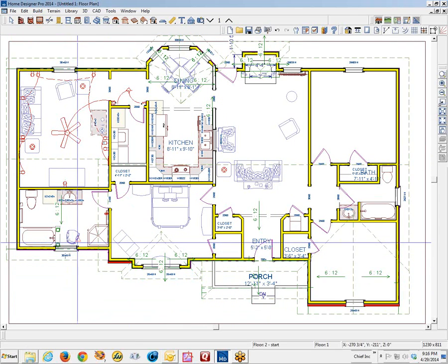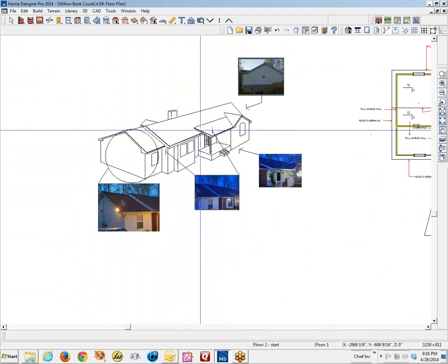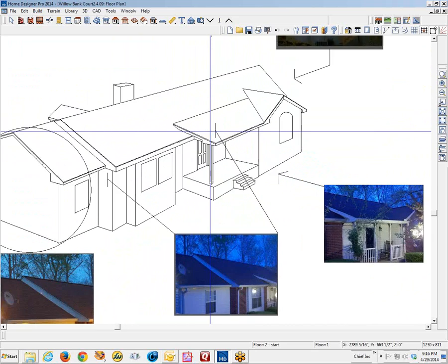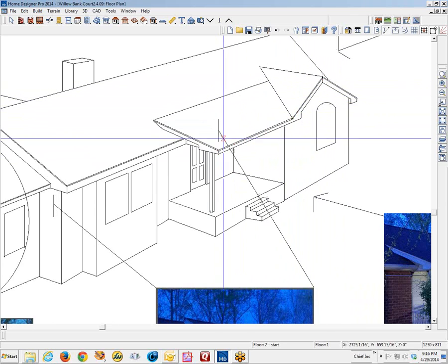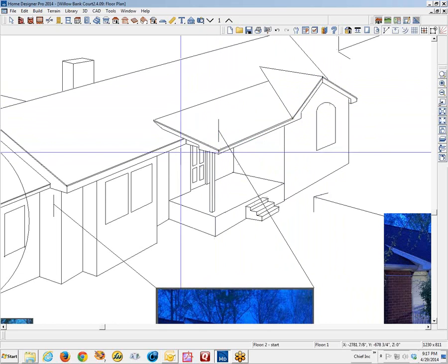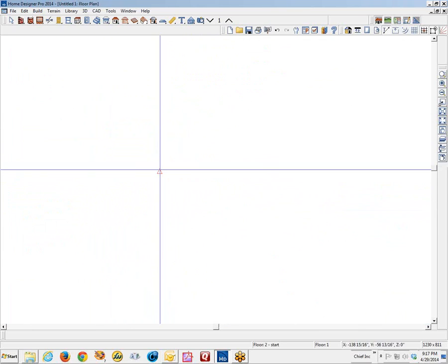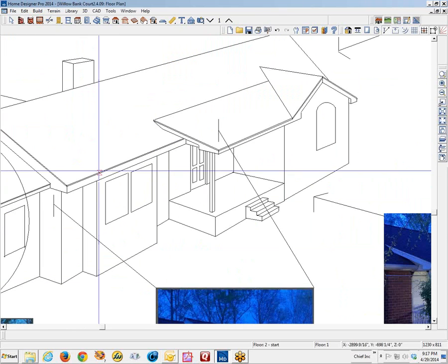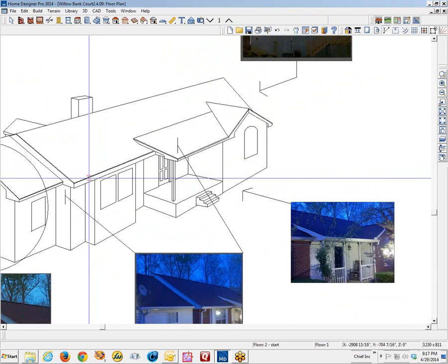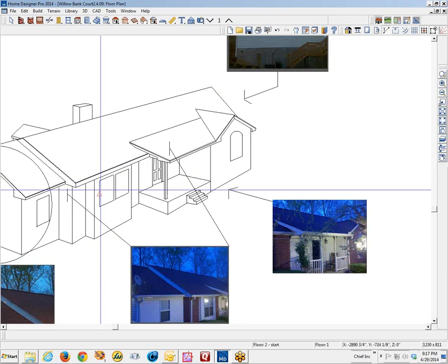Okay, now here in the front, I'm going to hit Control Tab to go to the other plan. Now it looks like this roof plane here matches the fascia top of this gable over here. And I assume it's probably matching the fascia top of this roof plane here. So that's what I'm going to check next. And oh yeah, there's no gable there, so I'm going to get rid of this hip. So you've got that, it's coming straight out. I don't think that's going to happen unless you build the roof plane on this outer wall.